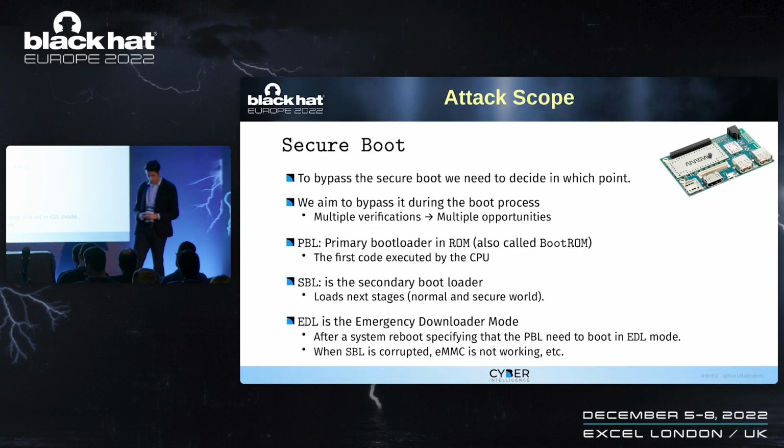So if we want to bypass secure boot of this kind of devices, first we need to know at which point, because you can do it at different levels. You can do it when the system is fully running. You can try to glitch an application, glitch the kernel, glitch the monitor, glitch whatever, right? So we think, and we'll explain in a minute, that in some cases the earlier the better, so we aim to bypass during the boot process.